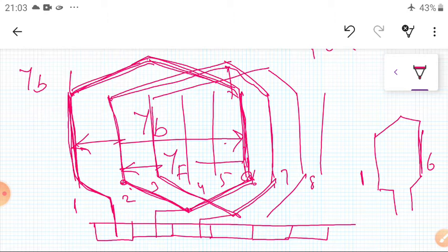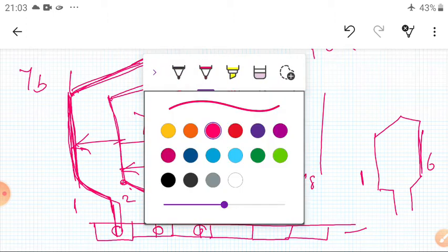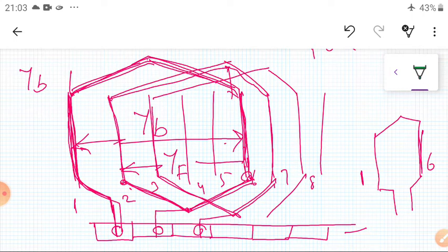The commutator pitch, you can see one example. This is the commutator. So what is the commutator pitch? The first coil is placed here, the second coil is placed here, the third coil is placed here, and we place them consecutively. The commutator pitch is the distance between the two commutator segments which contain the two ends of one coil. You can see that this is one coil. For example, I take another color. If we take this coil, so this is a coil.